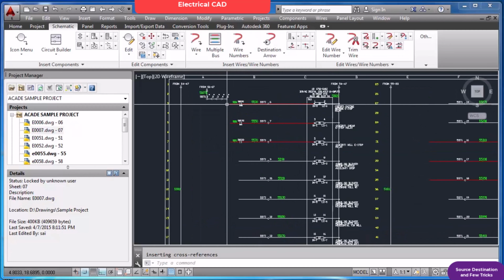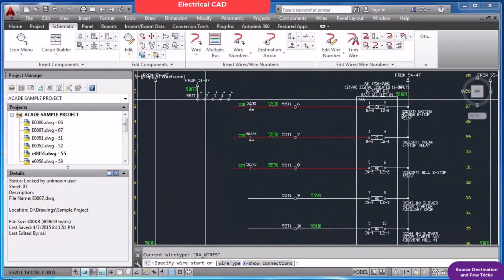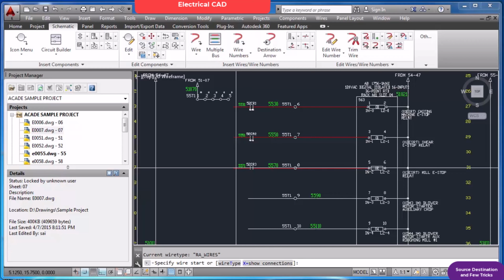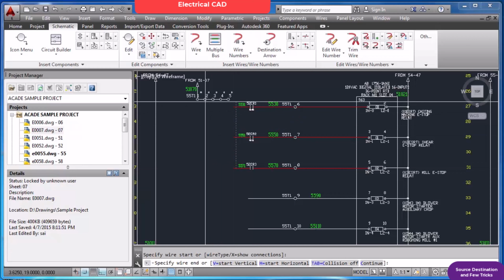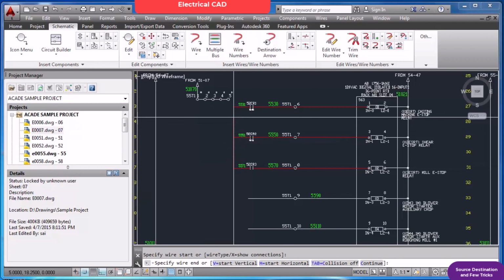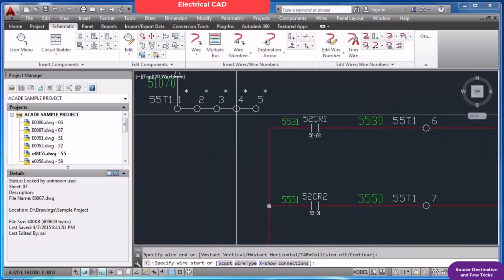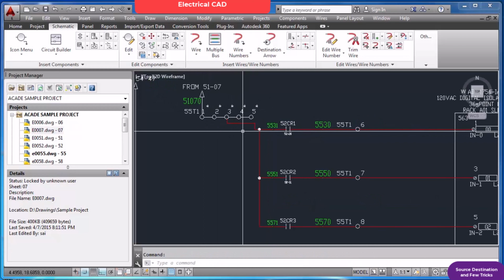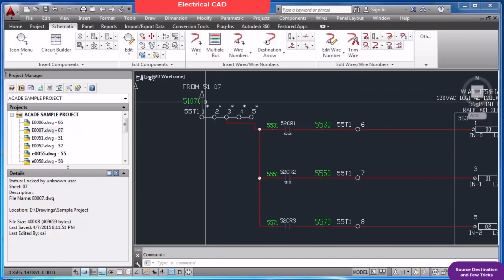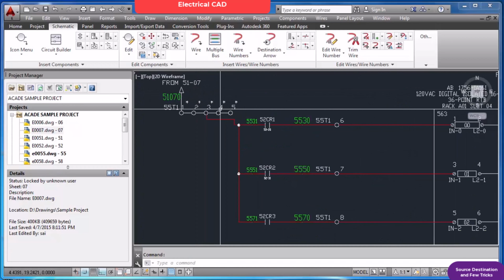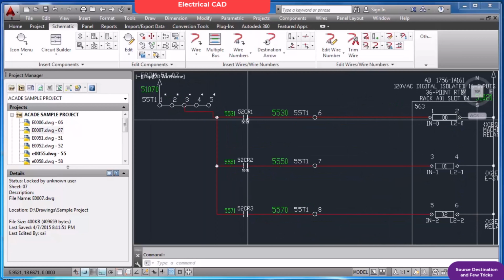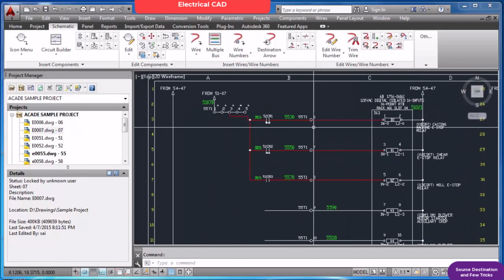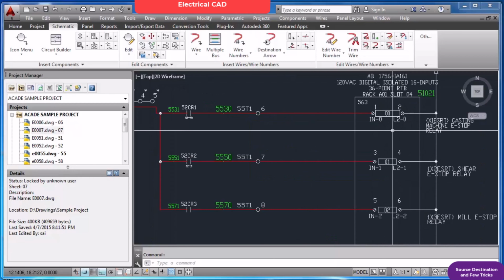Don't worry. So I will connect. See, in this case you can note one thing. I have connected to this particular point. This 110 volt AC is coming from some other source. So basically what I did is I have used one NO contact of all the 3 relays here. So once that relay gets picked up, the card will get a feedback. The PLC card will get a feedback.